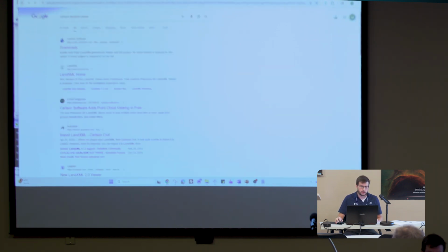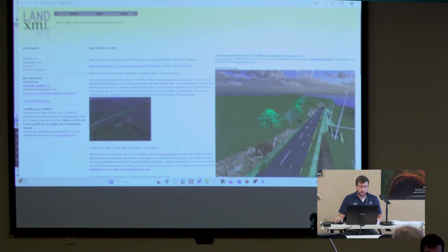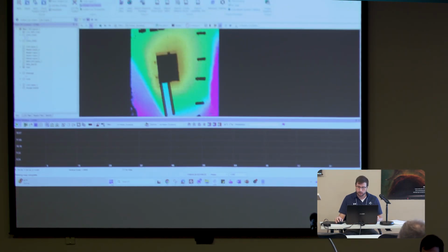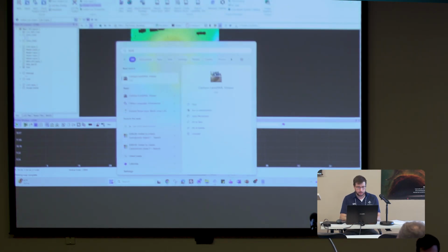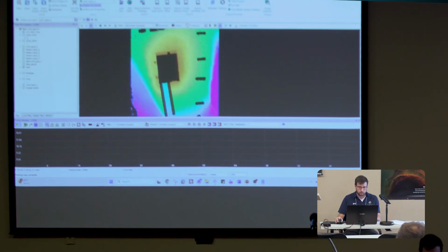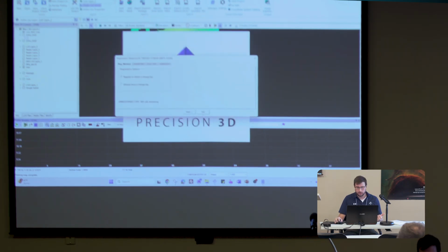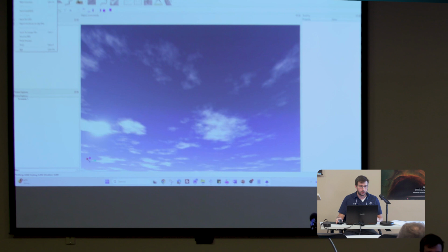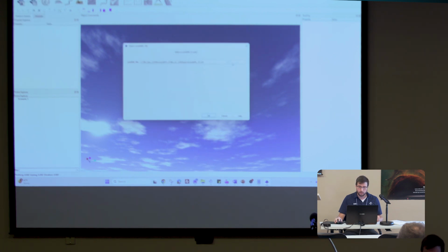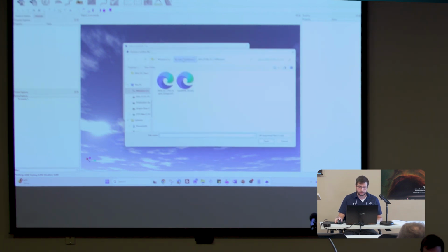Oops, wrong one. And it's bringing you to landxml.org. That's where you can download the free viewer. So I'm going to go ahead and open that up and look at the LandXML we produced. This is just a free viewer that you can use. We go to File, Load LandXML, and we'll go to that file I produced. Click Open.